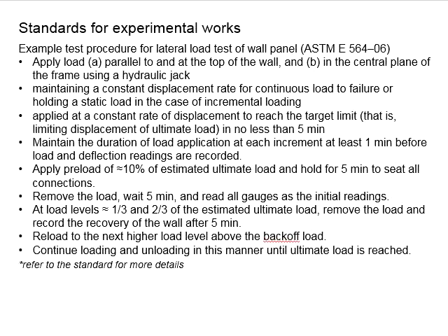This will be the third cycle where you're going to fail the specimen. This is a typical 3-cycle loop applied laterally to a wall panel in terms of the static load. It is not a dynamic load and it is not a cyclic load. Based on the testing procedure here, you will be able to acquire the stiffness of the wall panel as a resistance to the horizontal load during the first, second, and third cycle.